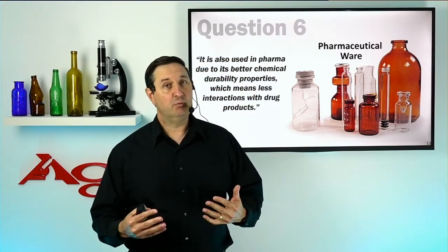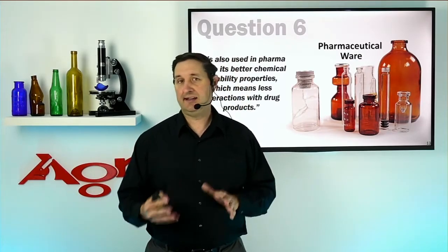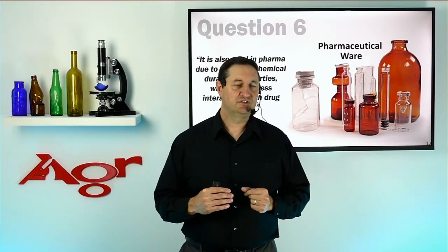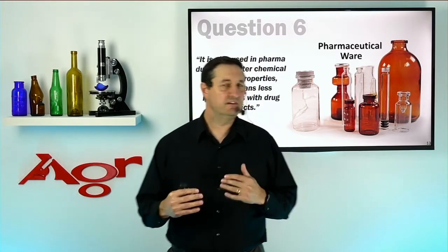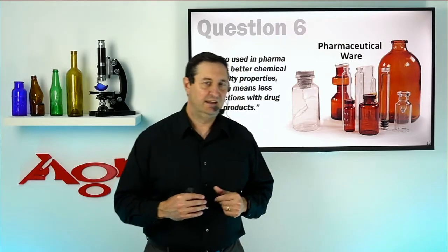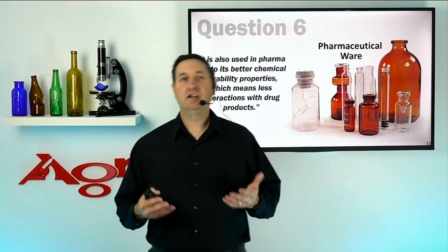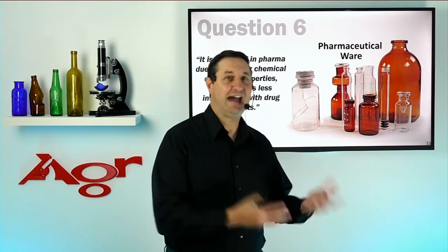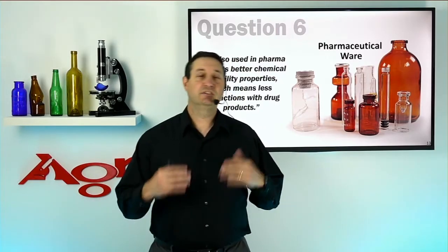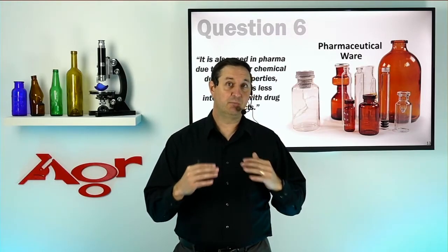But in reality, when it's out in actual use conditions, and as both bottles pick up damage through handling, they're going to pretty much end up at a very similar surface strength. And consequently, the advantages that we might have with borosilicate aren't really realized in performance. The other thing we need to realize is that when I add boron to the batch, that is an expensive additive. It also raises the melt temperature considerably. And so consequently, we're going to be looking at very high cost to make a borosilicate.